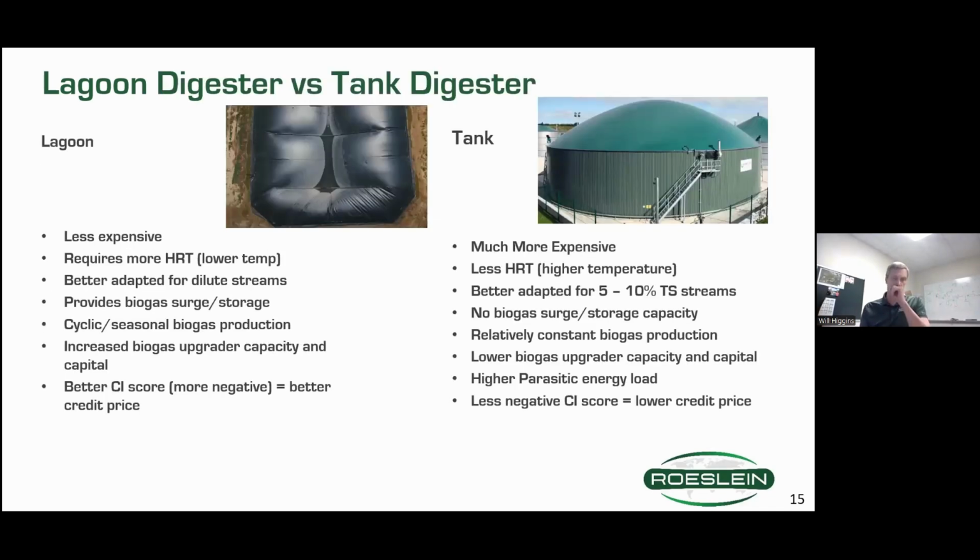And that leads me into a discussion of why a lagoon digester versus a tank digester. So a lagoon digester is much less expensive. You're paying for a cover. If you've already got a lagoon there, we're putting a plastic HDPE cover over the top with some ballast piping.